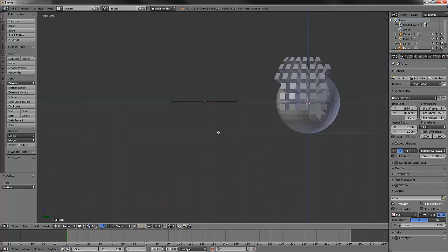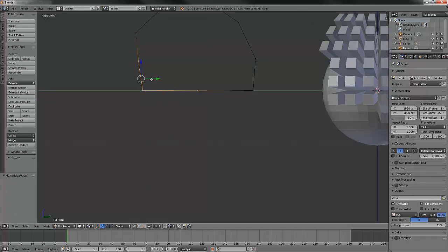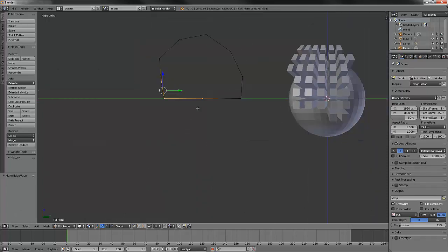I'll select the right vertex and hit E several times, choosing a new spot to create a vertex each time. Now, when I get near the original left vertex, I'll make sure that my last created vertex is still selected, and I'll then select the original left vertex, and I'll hit F for fill. The line will fill in between those two vertices, and now we've created a complex shape.